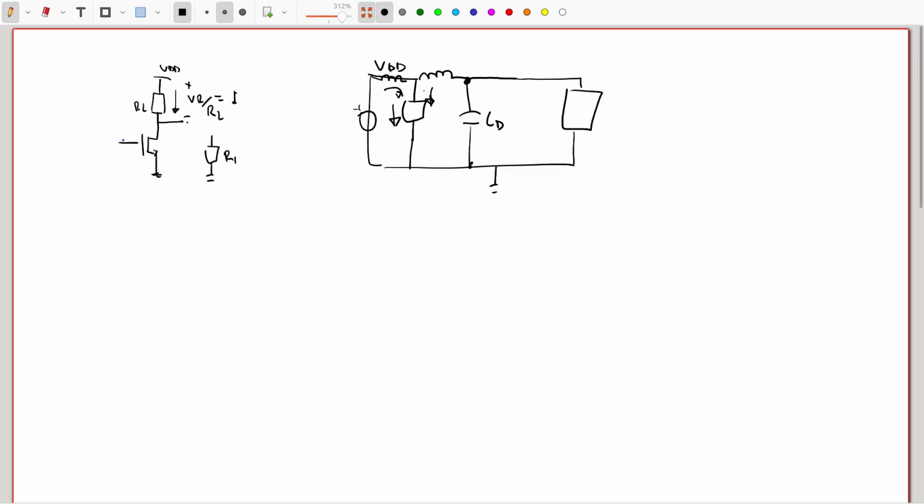So I can probably connect a capacitor here. And as long as the capacitor is large enough so that it doesn't affect the signal bandwidth, then these two nodes will be AC coupled. So that is a coupling capacitor. We can put it on the input, or we can put it on the output. I can also use them in the feedback, as we will see very soon.